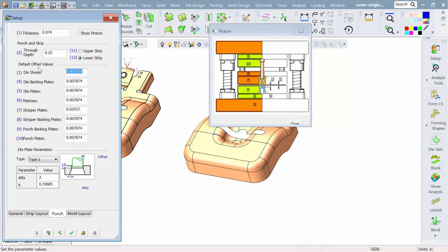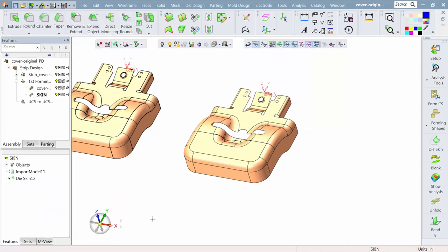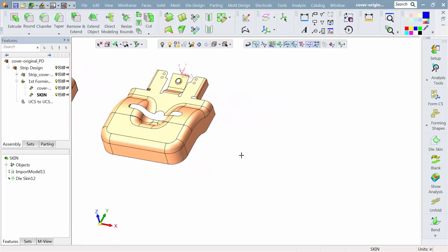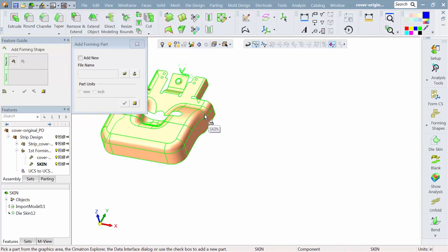Now, seeing that diagram, we're setting the distance that the punch will travel through the steel on shaping it and cutting it. And then we're setting up the clearance now for each of those components that you see on that diagram. Some of these are going to be a simple slug drop like going through a shoe. Others we're going to do a shear, so we'll put in the 10-12% you would expect. Others like the die backing plate, we're not going to have a hole. The punch holder plate, that's going to just basically be the retainer, so we'll put in what our slip fit condition is. Now we're selecting the type of die steel we want. Typically we see straight land, 1/4 inch with a few degrees of relief. So that's our preference. That's the way we want to design the die. Let's save that in the setup. Now that information is our go-to information throughout this project.